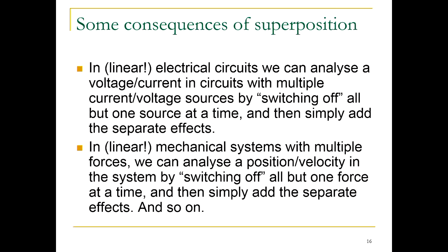You consider another circuit where there's only one source, and then you calculate the current due to that source. Then you consider another source, and calculate the current due to that other source. And in the end, you just add all the currents you obtained. That's the superposition principle. But this would only work for linear circuits. Often you go over this quickly. Only linear circuits would allow you to do this.